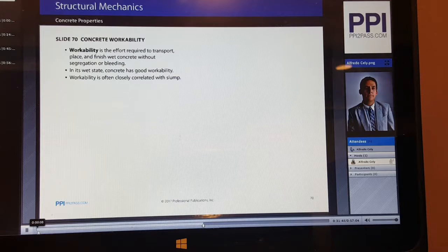Table 49.1 of the CERM gives typical slumps by the application of concrete. Typically, a structural concrete requires a slump between 1 inch and 4 inches. Self-consolidating concretes can have very high slumps. In these concretes, an alternative spread test is performed. The test measures the diameter of the slumped concrete instead of its change in height.